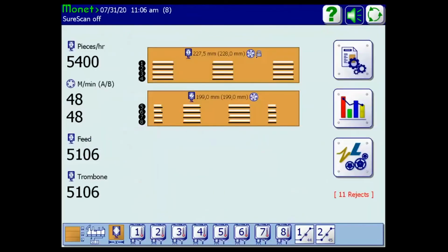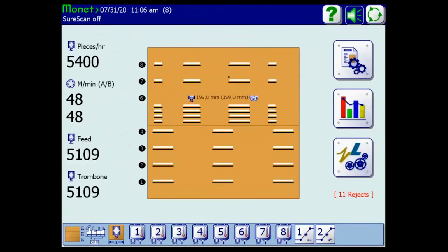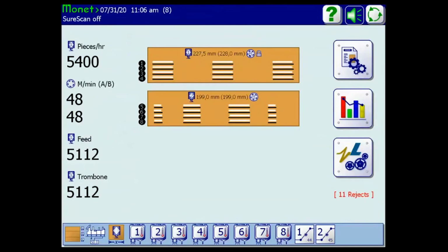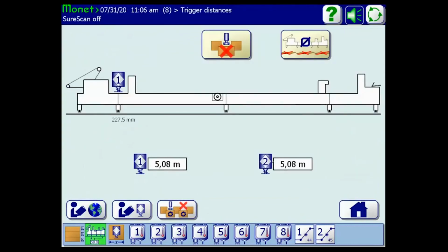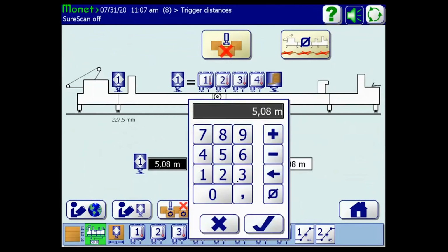running on encoder A. I'm sorry, it's backwards right now, but that's how we can have one trigger assigned to one speed reference and another trigger assigned to another speed reference. They're showing both as B right now because we tried relearning distance, but I'm using one trigger for both trigger 1 and 2. So basically I've got a Y cable. I've got one photo eye and a Y cable. That's why.